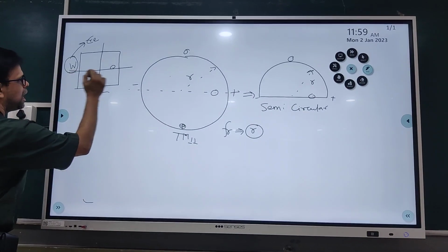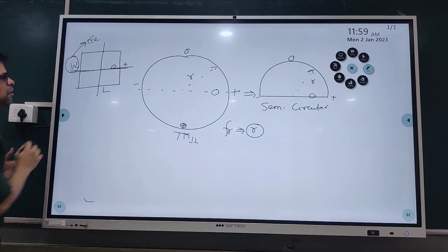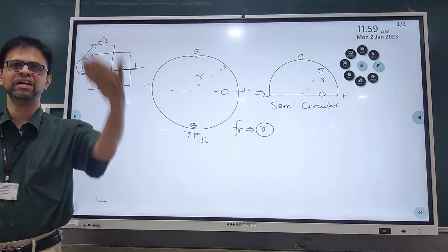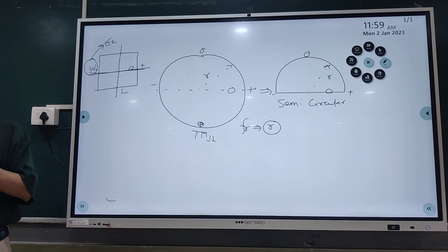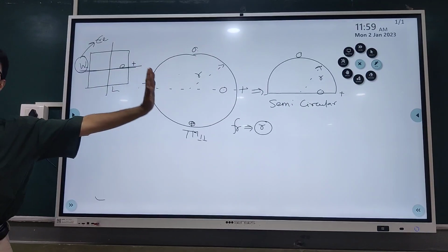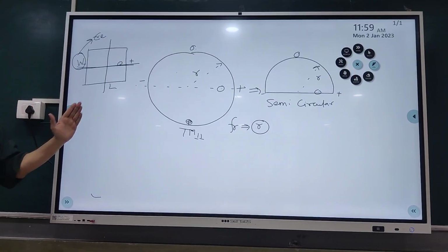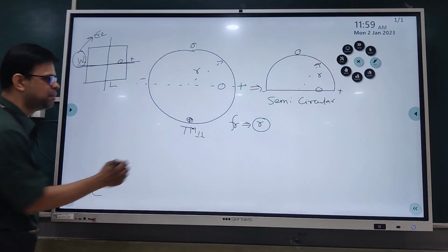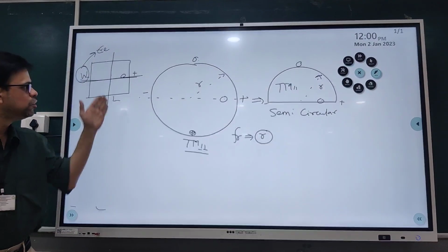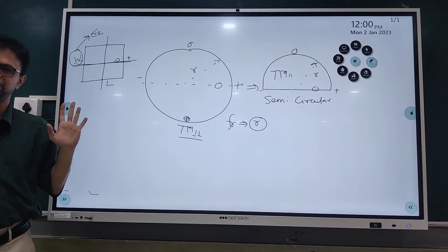Unlike in this case, if I use a half, because the same principle can be applied over here also. So if I use the half of the geometry with respect to the fundamental mode, here width is getting affected. That will affect your effective dielectric constant, and because of that, your resonance frequency will change. Same concept, same equivalence can be dealt over here, because ultimately the width of the patch is also reduced. The area of the patch is reduced. But the effect of variation in the frequency of this fundamental mode TM11 in circular and semicircular are lesser. You will see a drastic variation in the frequency here because L and W both decide your resonance frequency.